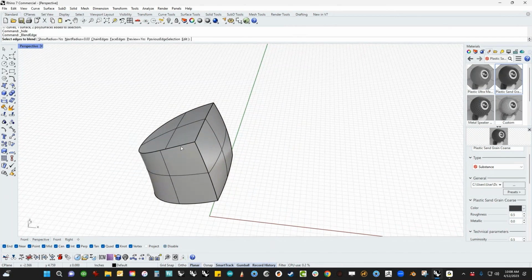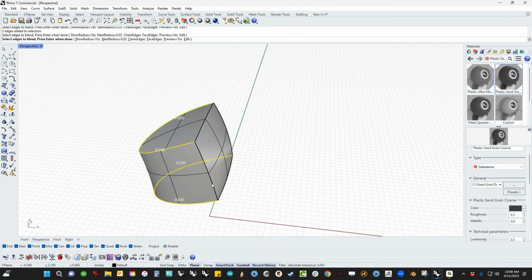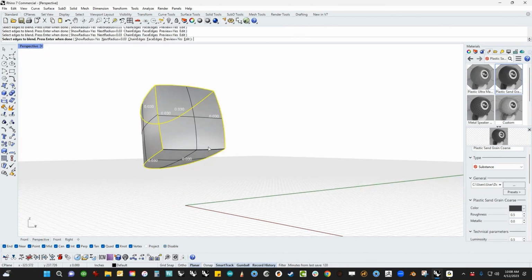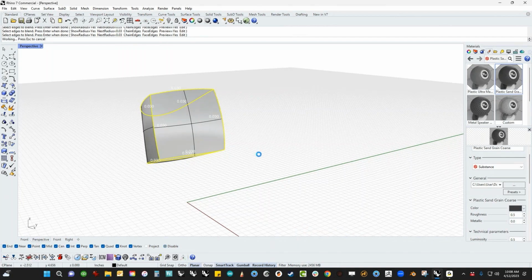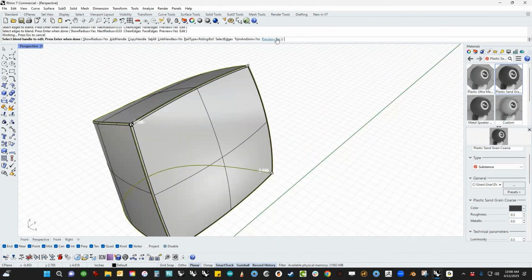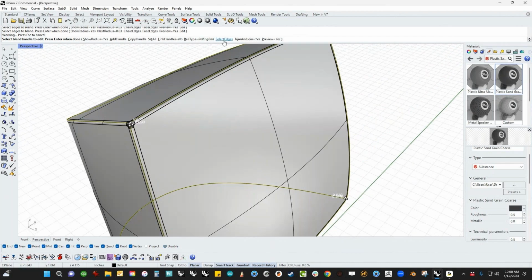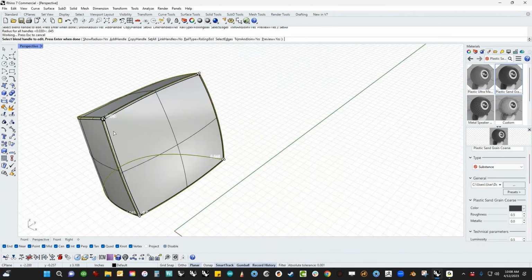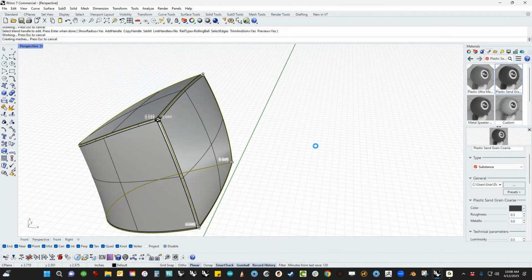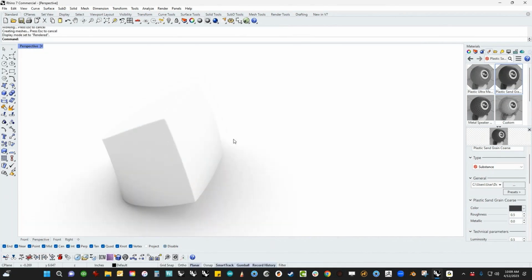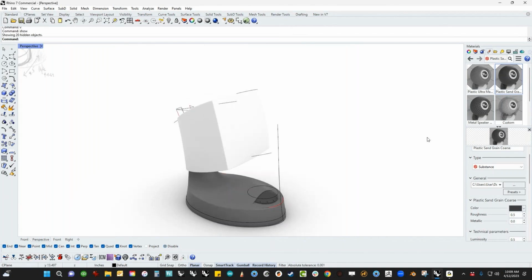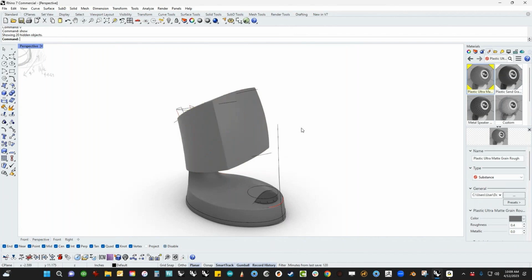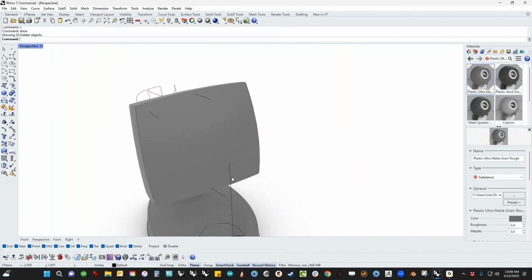And we're going to just do that with the blend tool. I always run my previews on so I can see what they look like. Let's go just a little bit bigger. So I'm going to set all. And then let that run. And the blend, what it does is it just gives you really nice blended edges instead of that kind of rolling ball fillet, which I just am not a fan of. So let's add our plastic material on there. And then we just need to design a speaker grill.